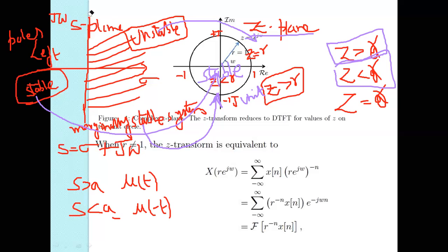And the marginally stable system is when any one pole is present on the imaginary axis, then we can say the system is marginally stable, and it maps to the Z plane on the circle. This is stability between the S plane and the Z plane, and the mapping also. Following, my dear students.